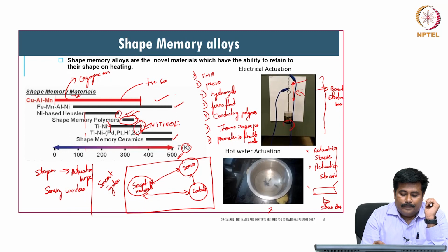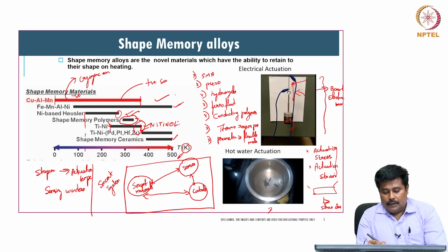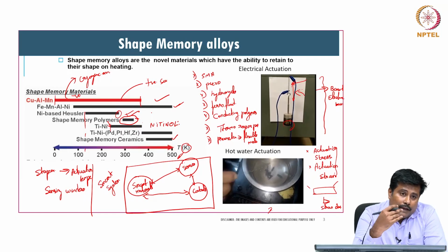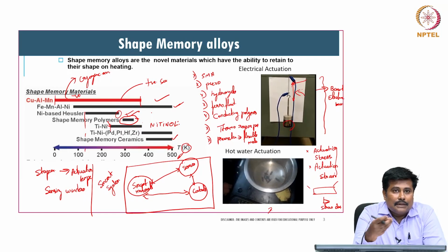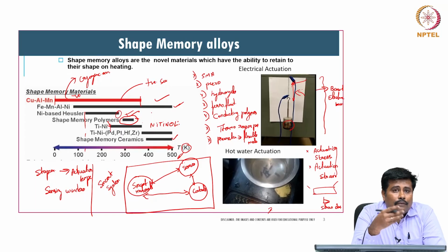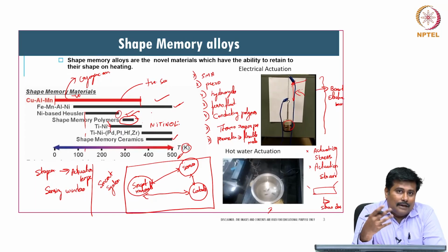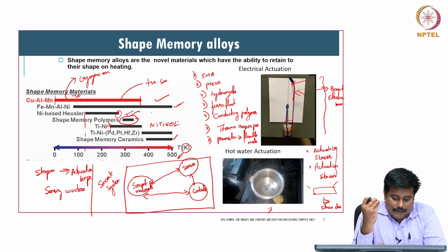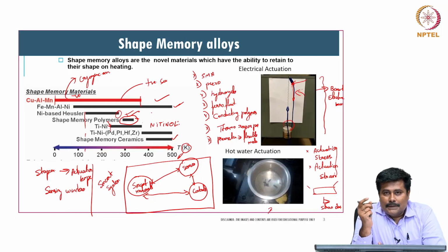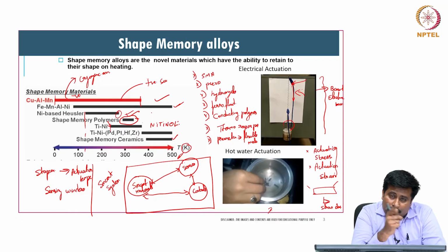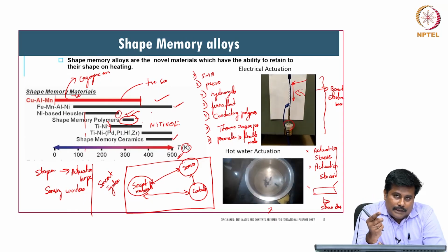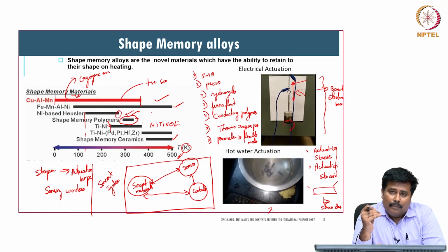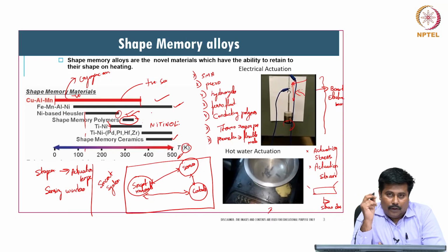130 degrees Celsius. Then there are several research groups who have attempted adding certain amounts of intermetallic structures and intermetallic layers into it, which include Pd, Pt, Hf and zirconium based structures added to these nickel titanium based structures, so that appropriately we can tune the property of the shape memory alloy and make it workable for the customized environment or the customer's characteristics we are looking for.